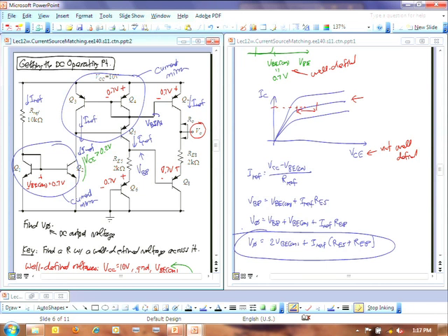Number 1. Yeah, it was the gain with the capacitors. Right. Yeah, that we shouldn't have done that. We should have told you zero frequency means open the capacitor, and high frequency means short the capacitor. The reason I was confused is because in lectures 6 and 7, you define high frequency gain and low frequency gain. It's like 1 over 1 plus s or something like that. s over s plus omega, something like that. So, are those the same idea?